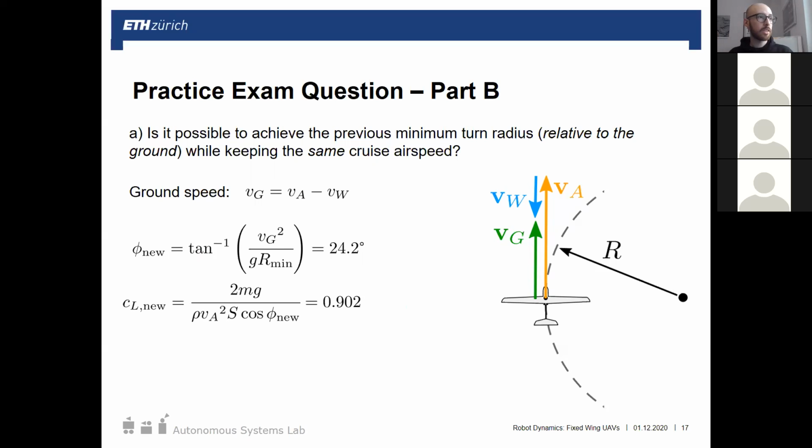The other thing is, even if it was a constant, so no geometric twist, but you have a constant chord line for your main wing, it's still very common to have an inherent incidence angle. So an inherent angle of attack away from the body axis for the wing. And again, this is done depending on the designer or the performance specs of the aircraft.